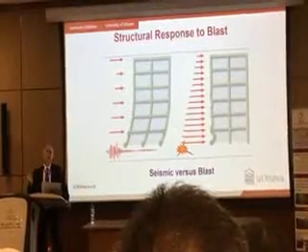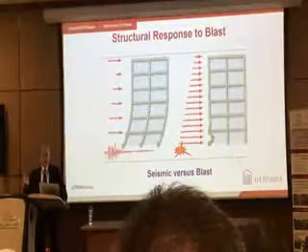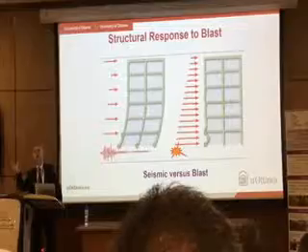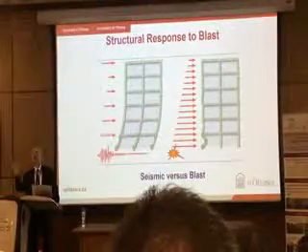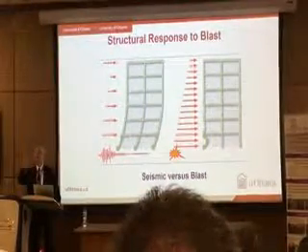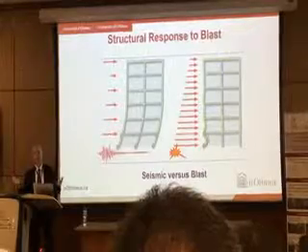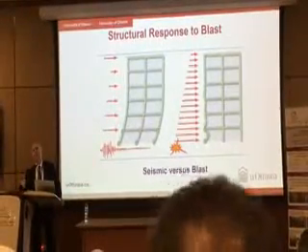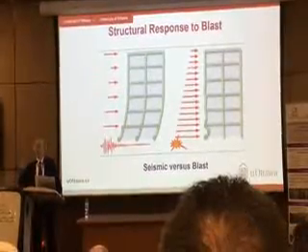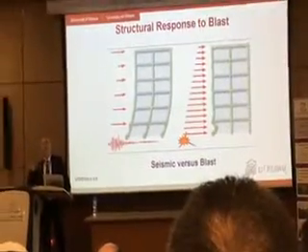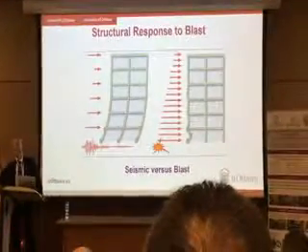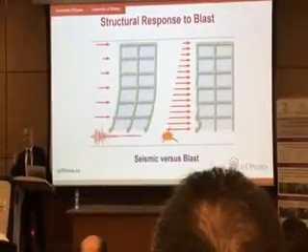This is all to say that the soil is so soft that it has a very long period. When there's an earthquake, this is what the soil does, right? And if you have a 2-story building, this does that, so they don't talk to each other. Low-rise buildings, nothing happened. But they started developing high-rise condominium complexes. Buildings of about 20 floors started falling down. They couldn't understand why, because excitation was long period.